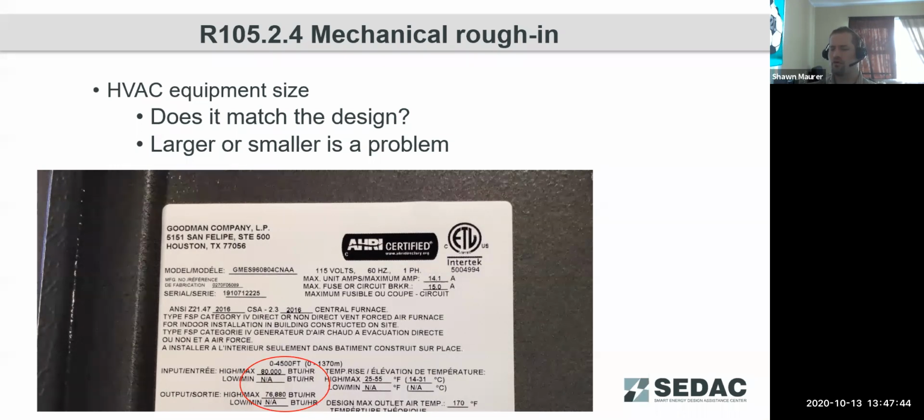And another note for oversizing, if that's on your AC system, you're going to have a significant problem with controlling humidity in the building. It's important for humidity control that a system be able to run for more than, if I remember right, about 15 to 20 minutes in order to get adequate dehumidification for a space. So proper sizing helps ensure that that cycle time is not so short that dehumidification does not occur.